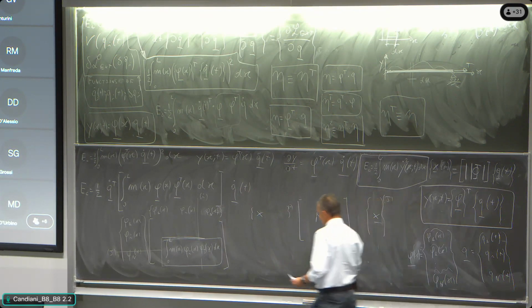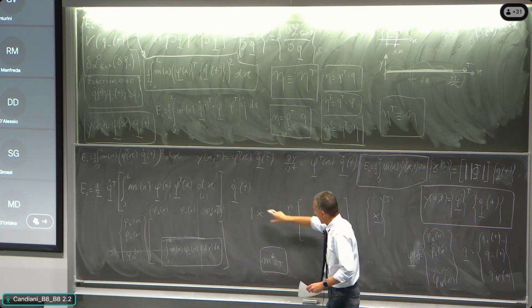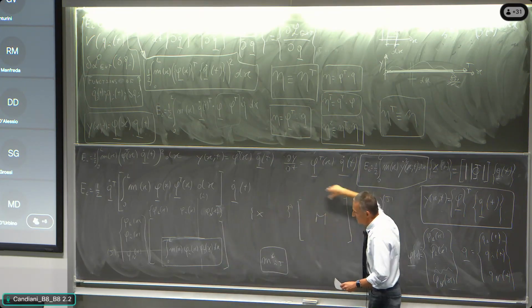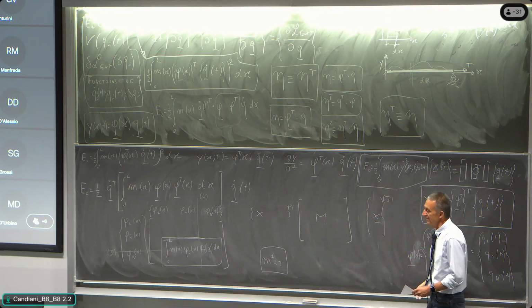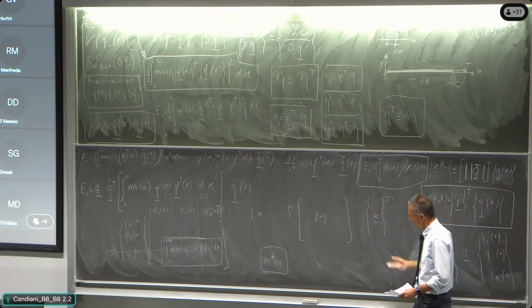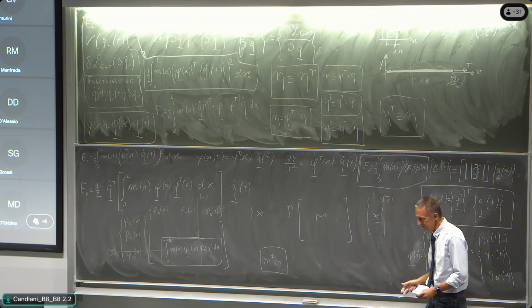Okay? So in the n degree of freedom, what we are writing is that the m star ij is eigenvector I mass matrix eigenvector j. And the orthogonality is that this product is null if I is different than j.